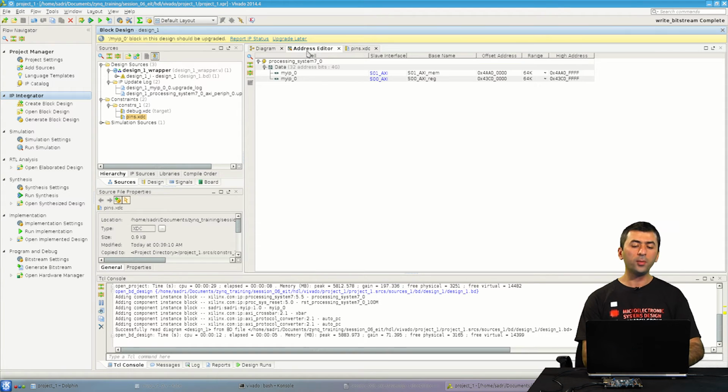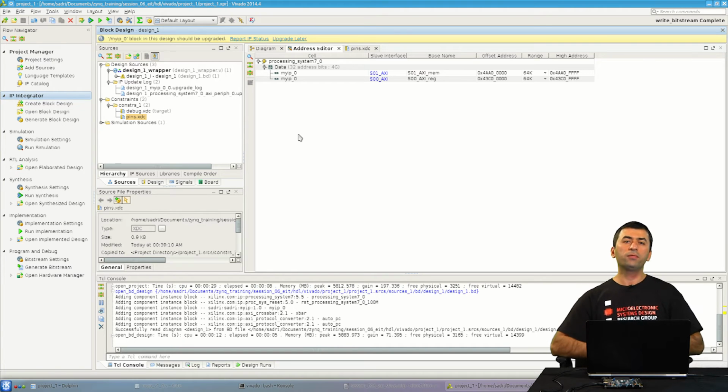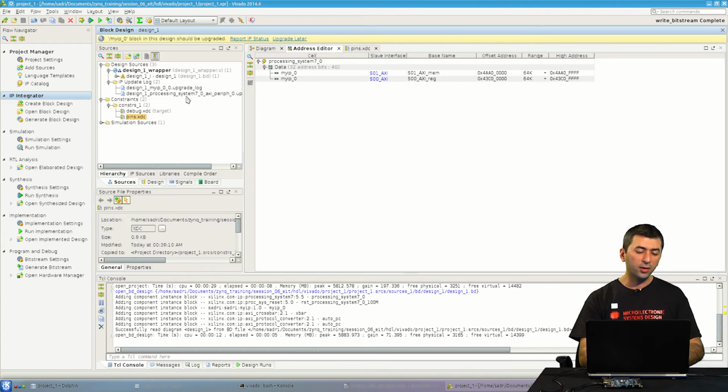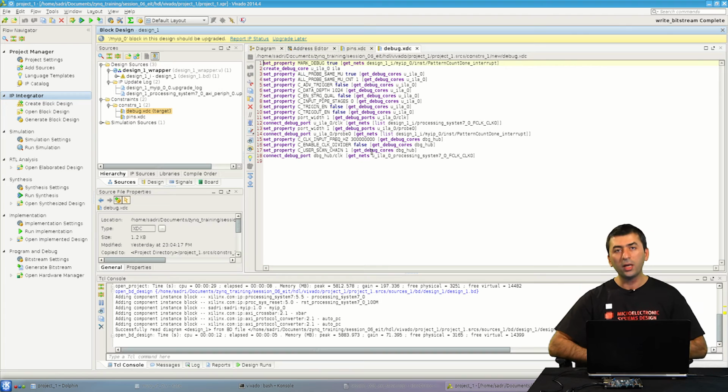Furthermore, for my tests, for now I don't want to write any software on the SDK. To check the interrupt, I use the ILAs, and I capture the interrupt signal over the FPGA using the ILA core as I described in previous sessions, and I watch it inside the waveform viewers of Vivado. I have done that before, so I have another constraint file, which contains the definitions for adding the interrupt signal to the list of signals being monitored by the ILA core.